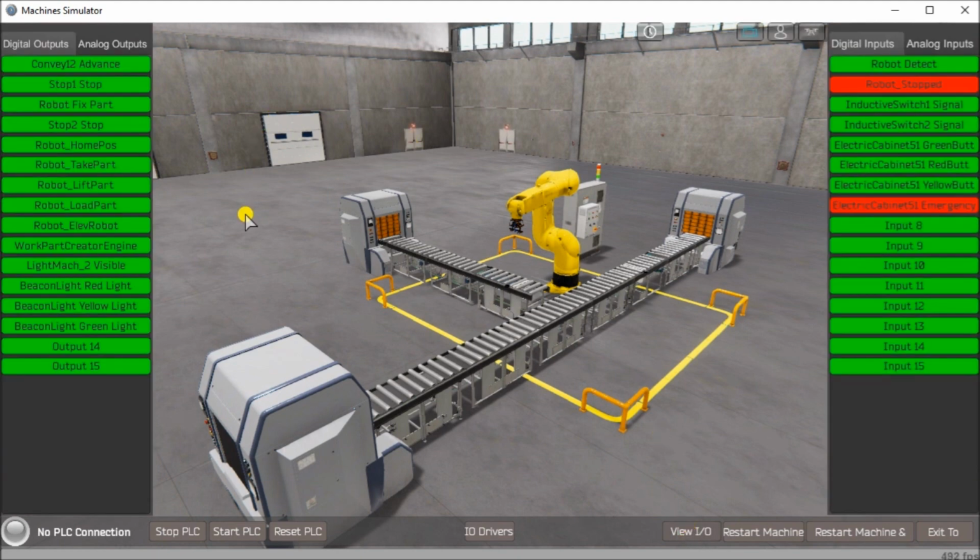Now, after we define what has to happen, we're going to find the inputs and outputs, which is step 2 of our EasyPLC robotic cell. Here we can call up the I/O, and as we hit each bit, we can see the operation. So here we have stopper 1. We turn it on, turn it off, and you can see it pop up and down. Stopper 2 is right here.